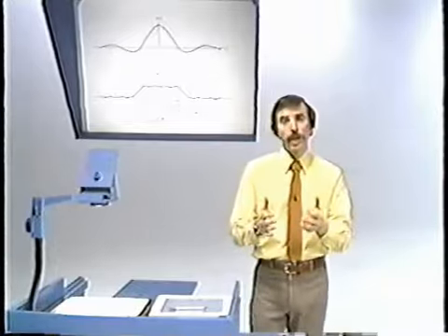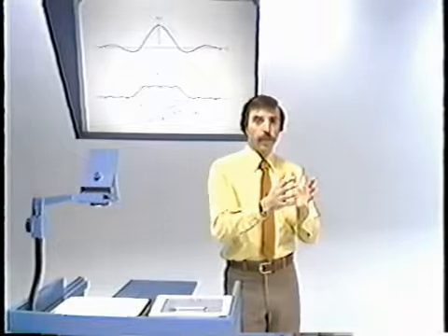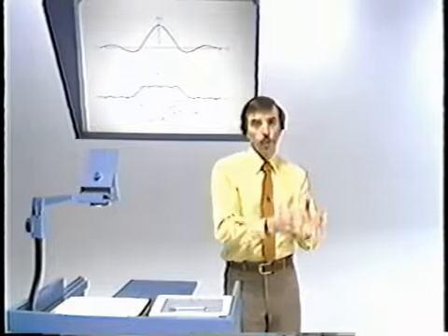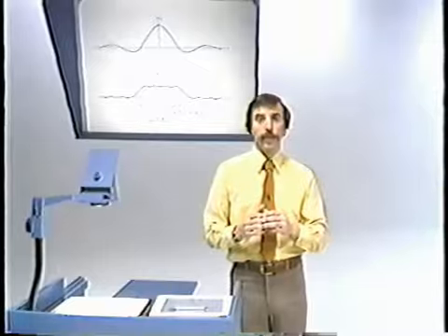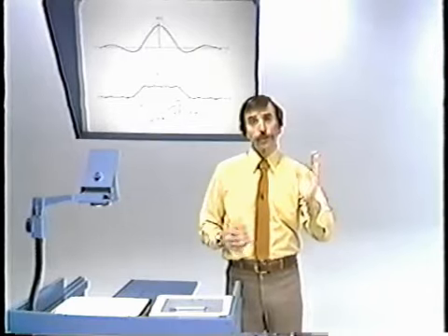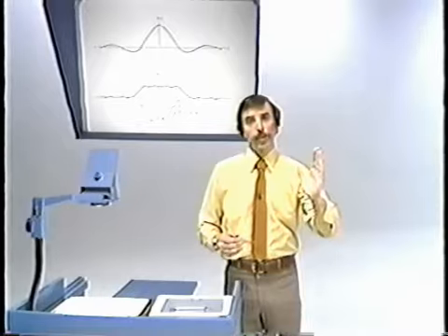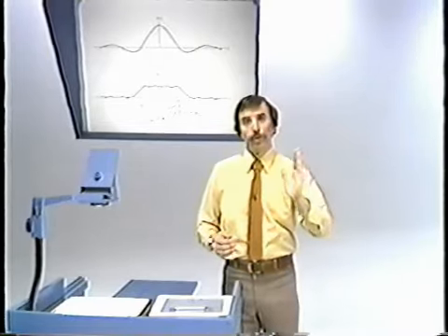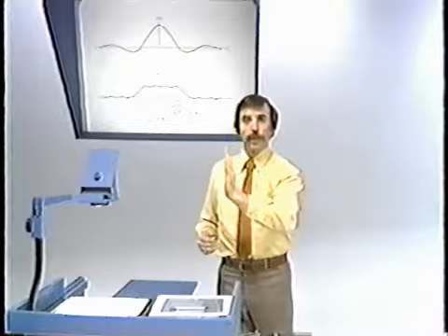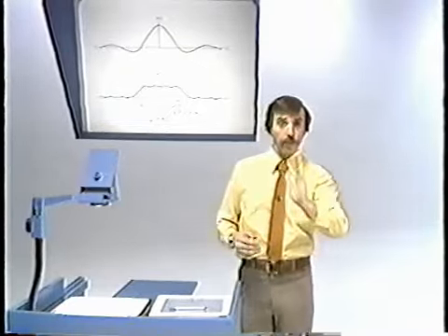And so keep in mind that as the input frequency sweeps past half the sampling frequency, whatever sampling frequency we happen to be looking at, then because there's no anti-aliasing filter, we'll get aliasing. In other words, the frequency in the digital filter or discrete time filter, as we sweep the input frequency up, will move up in frequency until we get past half the sampling frequency, and then essentially we'll move back down in frequency.